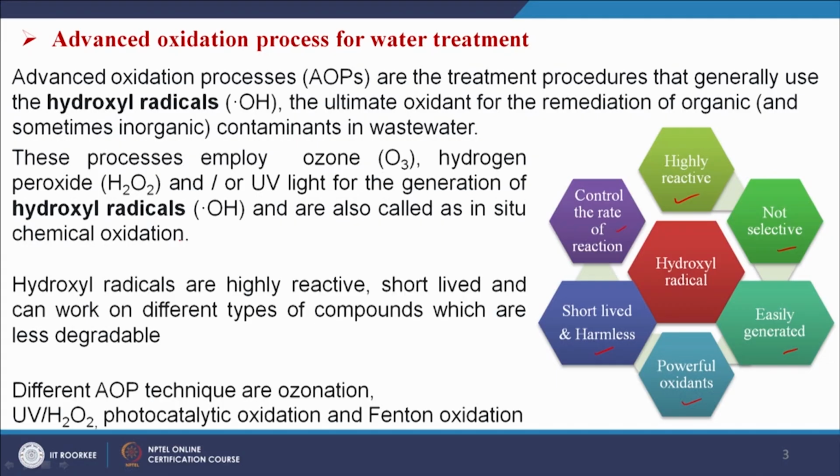Photocatalytic oxidation is also under this category, and hydroxyl radicals are highly reactive, short lived and can work on different types of compounds which are less degradable. Different AOP techniques are ozonization, UV, hydrogen peroxide, photocatalytic oxidation, Fenton oxidation etc. So, we will be discussing all of these techniques.